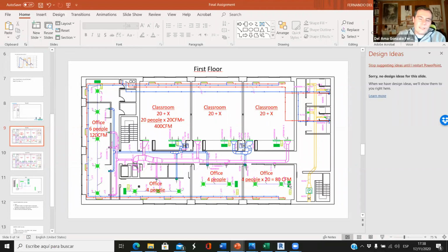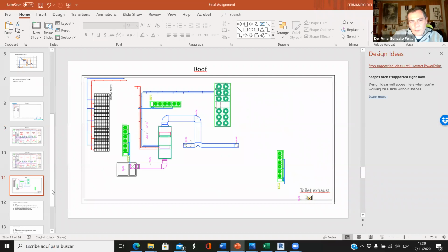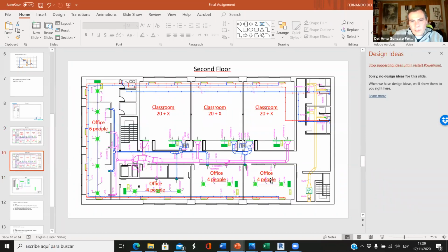So if you look at the TDS center, we have the same, and this is an educational building. So this is the usual strategy. We can provide all the heating and cooling with the air handling unit, with the air chiller and the water heater. But if something goes wrong, we need a backup system. So here, the backup system is the outdoor heat pump and indoor split units. Okay, so in the TDS center, we have both. We have the air handling unit, and we have split systems